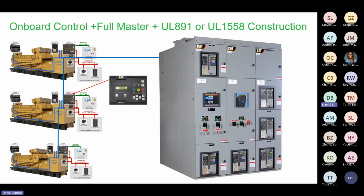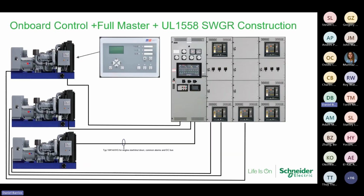Okay? Caterpillar does a very similar thing. The only difference is, if you'll notice to the left side of that 3-section lineup, they are utilizing a dual gen section. Obviously, we're saving space, we're saving cost, we're saving money, okay? But you'll notice now that you do not have any of your analog meters. You're relying totally on that touch screen to see what is going on. And if that's acceptable, it's just pointing out those differences to you. Obviously, protective metering and relays can be added to this type of a Caterpillar lineup.